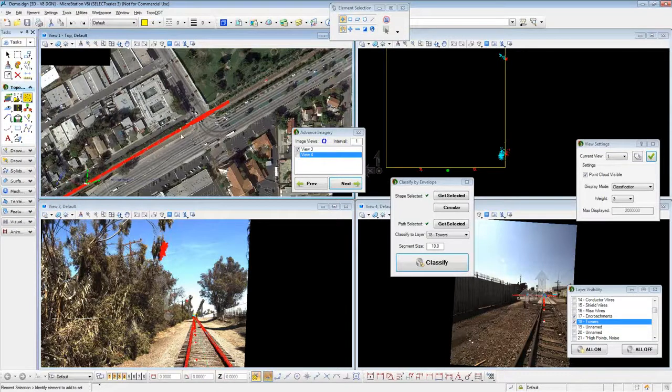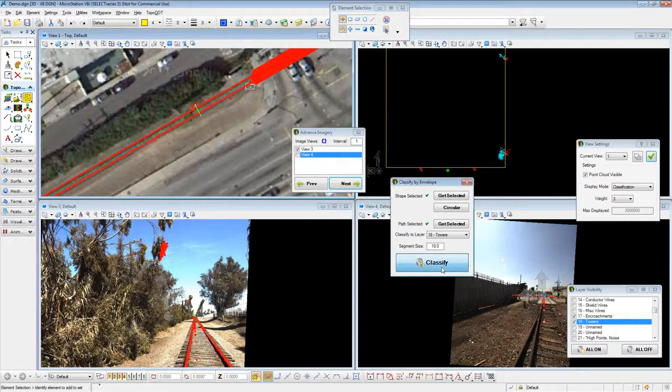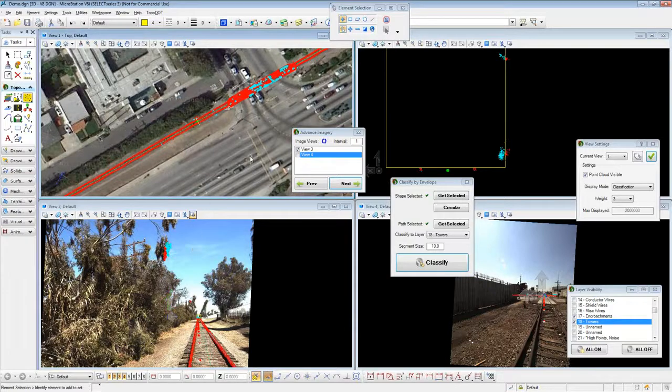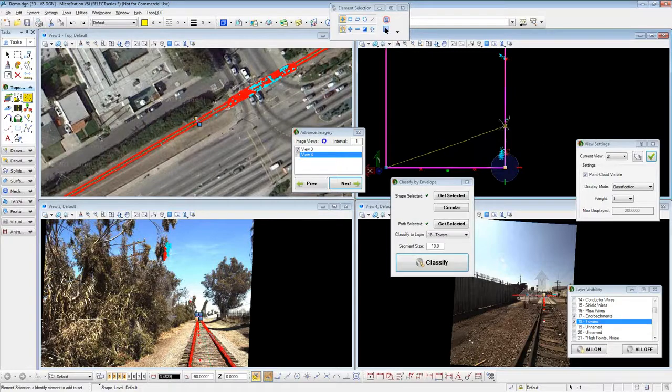We have a question. Would Todd's solution work if the bridge deck was on a transitioning super elevated curve? So I guess the question, Mally, is, if I understand it correctly, you have a super elevation, so your rectangle is going to have to follow that elevation around, right? What do you think, Mally? I think right now it's just going to stay at the orientation it is, correct? Yeah, you can define your shape to follow the super elevation, but it's not going to transition from a flat road to a super elevated curve or anything like that. It's going to stay one shape and follow that path.